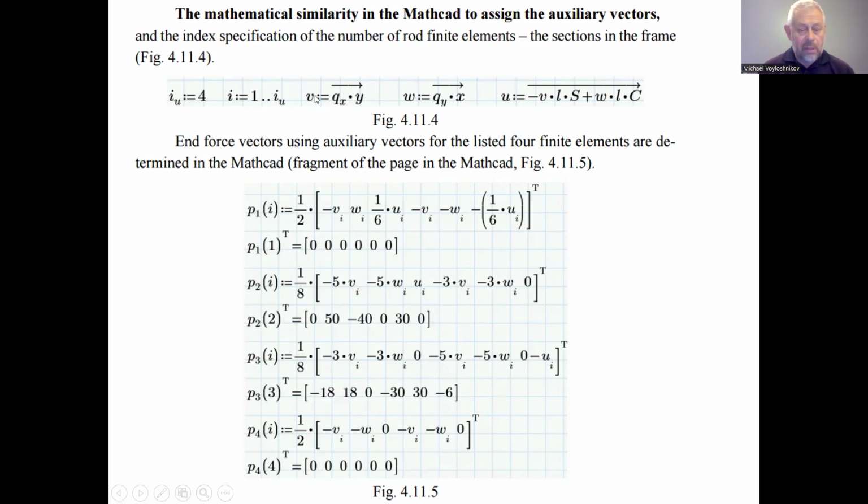It is not equality, it's assignment equal to the product of 2 functions. And we access next. We select by the mouse this product, and we access the Mathcad panel and the operations with matrices and vectors, and we can use the vectorization operation over the product of these 2 functions.